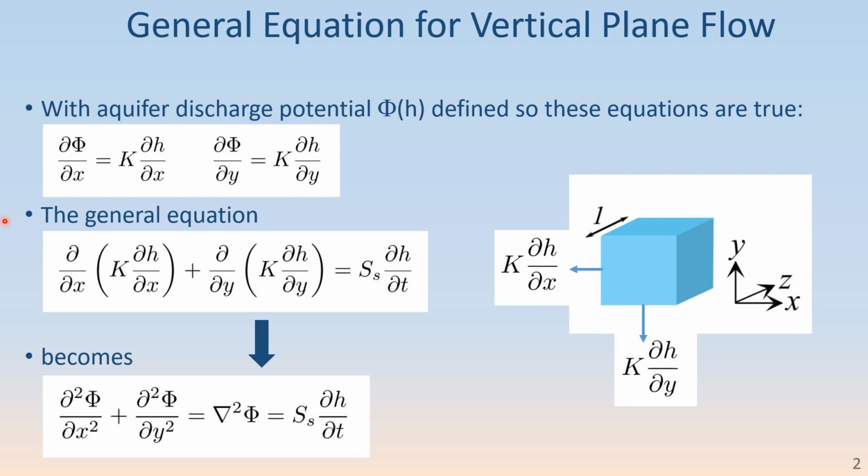And in vertical plane mode, we can use the same coordinate transformation to achieve general anisotropy characteristics in our models, and basically look at these equations over here as though it's an isotropic situation, or we're dealing with the equivalent isotropic coordinate system and hydraulic conductivity after performing that transformation.